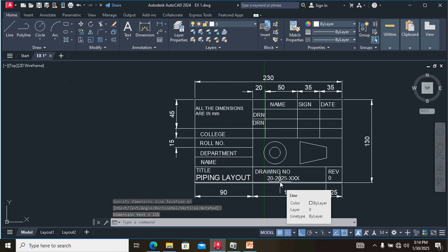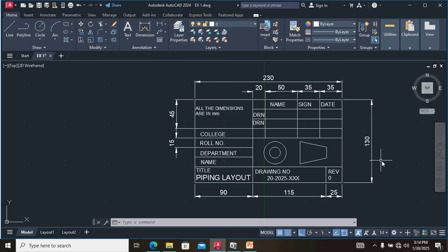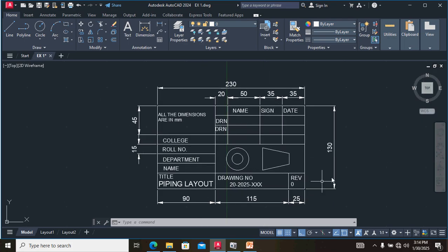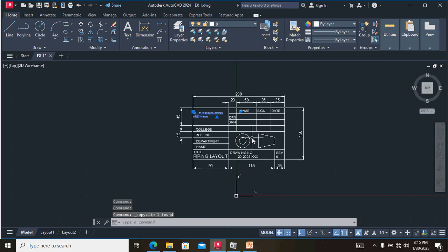Next, we have to mention its heading. For the purpose, we use text. So in this case, we don't click text again, as we already noted the values. Just select and copy. This title heading is Title Block. So click here and the text will open.